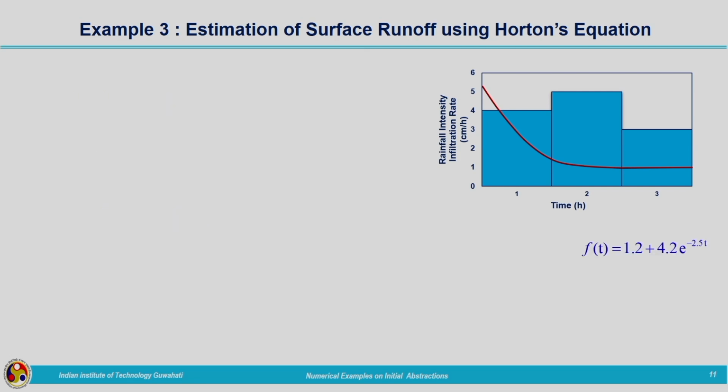So, now you can see up to a certain point, that point is corresponding to the meeting point of the infiltration curve and the rainfall hydrograph. When we were discussing the potential infiltration and actual infiltration, we have seen that if the f value is greater than the intensity of rainfall, all the water falling as rainfall will be infiltrated into the ground, right.